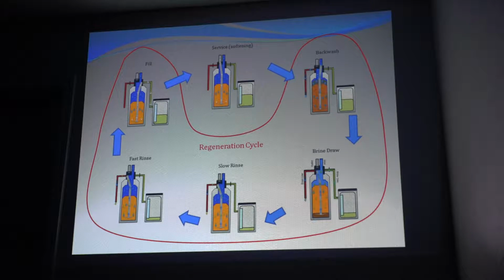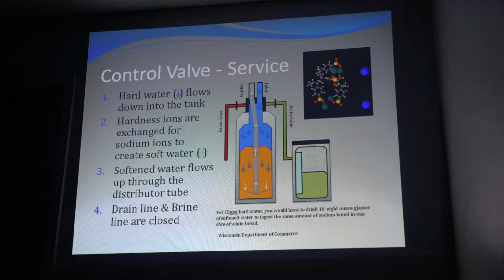Final regeneration step is fill, where the control shifts and it puts water back into the brine tank. The water will sit in the brine tank, creating a dissolved brine for the next regeneration, or for the next time the softener regenerates.